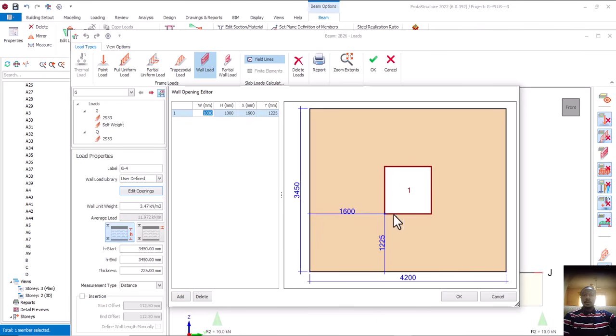So from here, this one is talking of width, the width of your window. If it's 1200, is that okay? Height. What's the height of this window? It's 1200. Then X. When you talk about X, from this edge here, that's what they're talking about. So I want to be close to this side. If it's 1, I'll just make it 1 as it is. It's already at center, I'll leave it. Then this one is talking about from here to this place, and our window is about 900 above the floor level. Can you see what I have now?